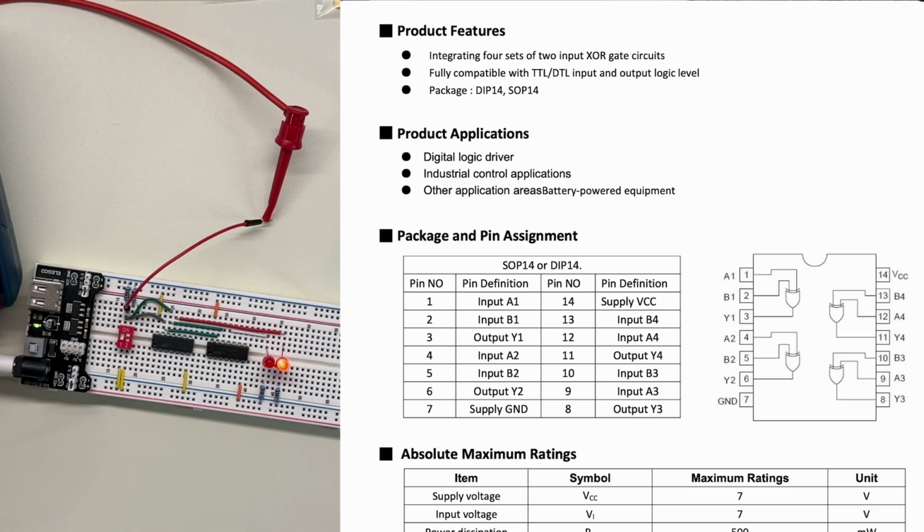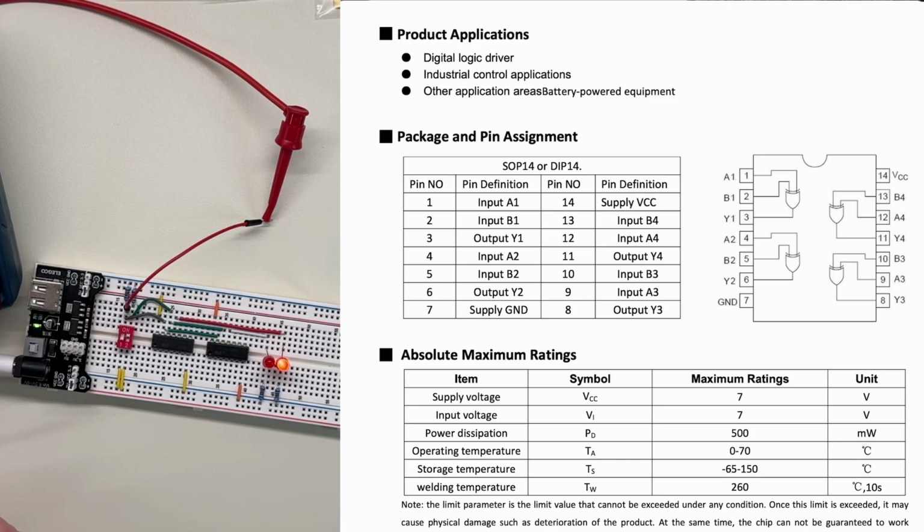That's kind of neat. So you can see here's VCC, here's ground, and we had hooked those up previously. And we use this gate on this side. So actually, I guess we use the last gate. I'm realizing now that the pin numbers actually go like this. For some reason, I had it in my head that they go down one side and down the other side, but they don't. They wrap around.